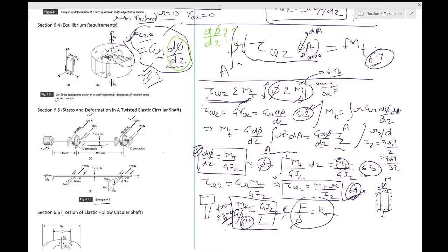First thing is, we always want to have the actual problem. Now we want to have a model, an idealization of this. So to idealize the situation, we represent each pulley loading by its static equivalent of a force of 120 newtons. So rather than taking this 120, the total force you can take as 120. Okay, it's not the same, but it's statically equivalent.